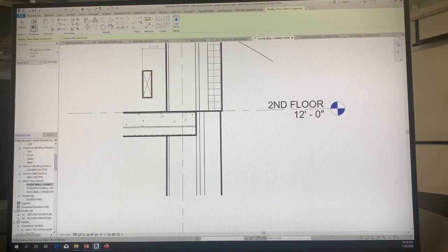And there it is. Now, obviously, press your space bar to flip it and place it right there on the top of my floor slab. Pick there. I'll put one down here, so space bar it so you can flip it, and put it at the bottom of your floor slab, right there. I'm going to put a double one at the top, so flip it, put one on the top of this one, again align it flush, and pick. Press escape.